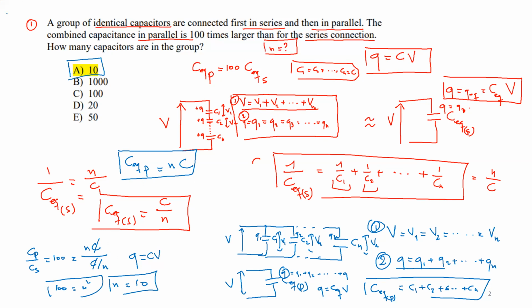Okay. So I wanted to remind you of this, you already know. Okay, and this you already know. For series, this is my equivalent resistance in series. This is my equivalent resistance in parallel. Now, something very important that comes again and again is that when I have capacitors in series, the charge is the same. Remember that, okay? And the voltage is added. Of course, in parallel, the total charge will be the sum of each charge, Q1 plus Q2 plus Q3, but the voltage will be the same. Okay? And we will use that extensively in what is coming.